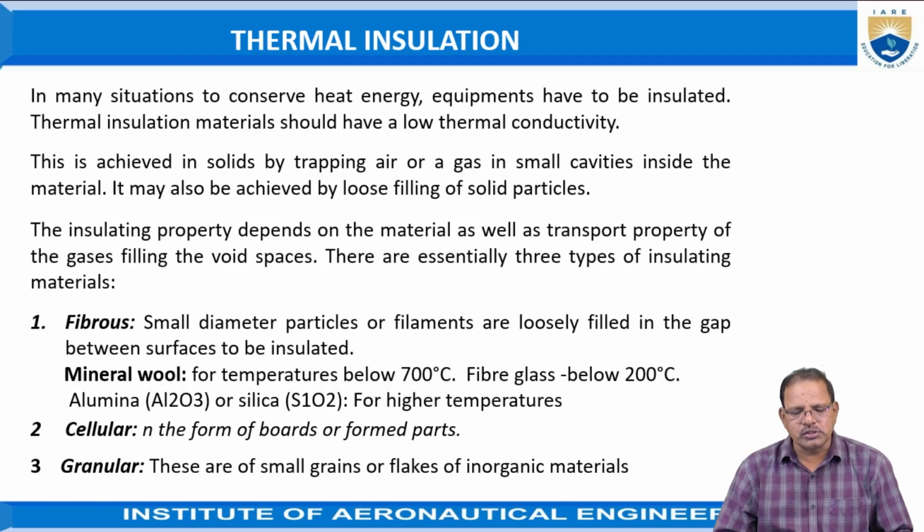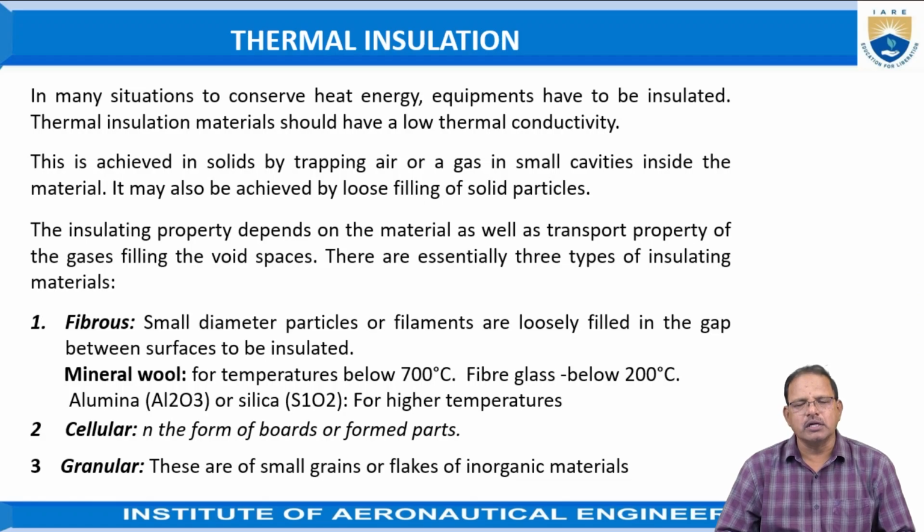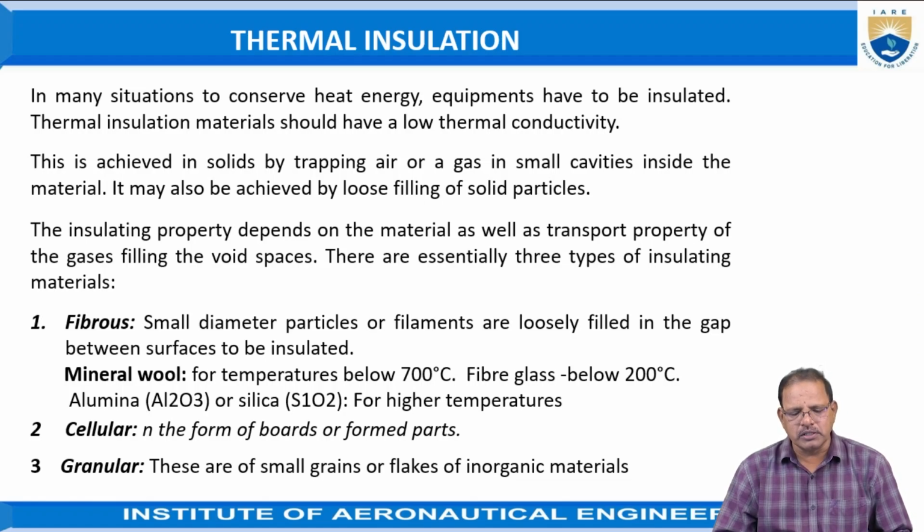So, in many situations, in order to conserve energy and to minimize the loss of energy through conduction and convection processes, the equipment used is called insulation. The thermal insulation material should have low thermal conductivity. This is achieved in solids by trapping air or gas in small cavities inside the material. It can also be achieved by loose filling of solid particles.